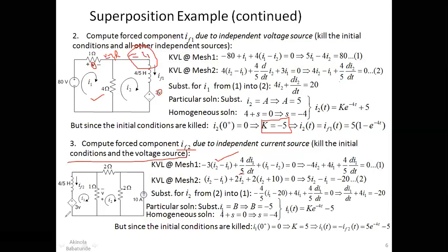Then we have the I1 dt because we have defined the current passing through here as I1. All right. So you have the I1 dt plus what can you see here? Plus V here. Okay, so we have passed through here and then we get here plus V. Again, V will be equal to I1 minus I2 because the current here is coming down and then our current here is going up. So you have I1 minus I2 multiplied by 1 will give us the voltage here.